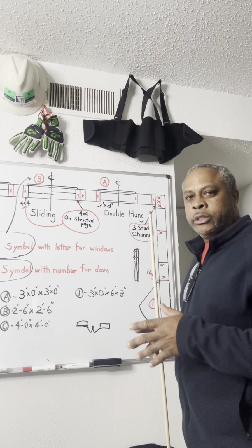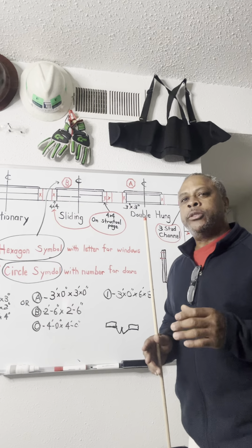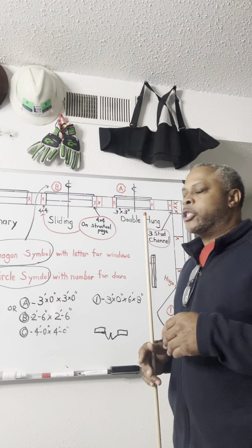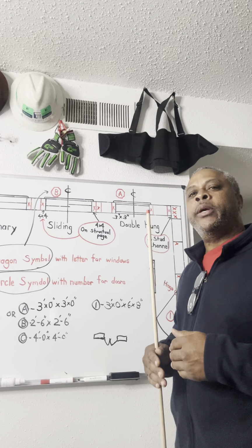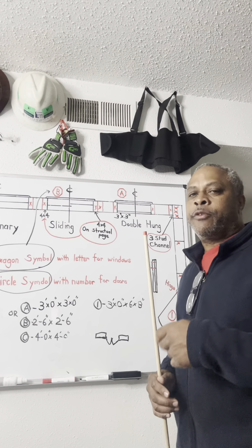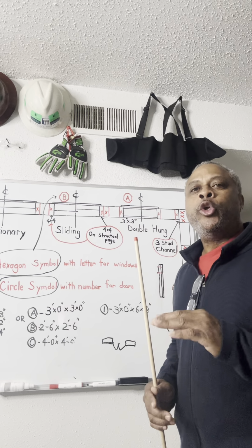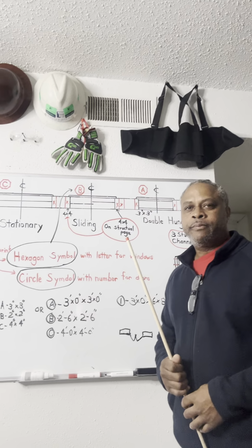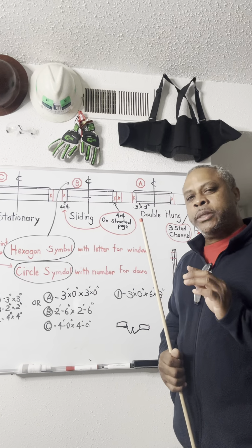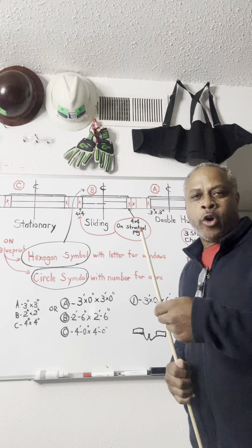Now, plywood, that's a different story. We don't want you to over penetrate plywood, because the plywood is put together and it's glued together, and it's called membrane layers. The membrane, if you break through the first two membranes, which is the nail is sunk in too deep, you will not pass inspection. The head of that nail should just be sunken in enough to where it's in the wood and not too far into the wood.